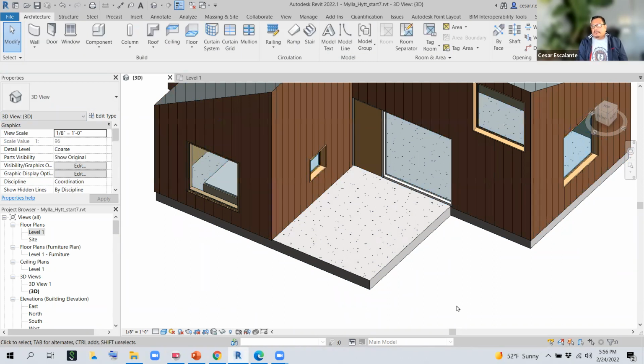And Revit comes with a lot of out-of-the-box fill patterns, and for the most part, they serve most of your purposes. But there are going to be times in which you need a custom pattern to reflect a specific type of floor, or a new floor pattern, or a mosaic, or a combination of different tile sizes. And so you can create custom patterns by importing AutoCAD hatch patterns.